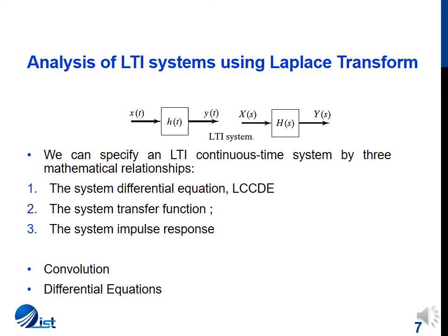However, in all of these cases, whenever we take the inverse Laplace transform, we have to be conscious about the ROC. And again, as I mentioned, if we don't have the ROC mentioned, we have to take all three cases. Also, for a differential equation solution through Laplace transform, if you are ever asked to verify that the solution satisfies the initial conditions, I told you how to split the solution into zero state response and zero input response, and how to verify your solution if asked.